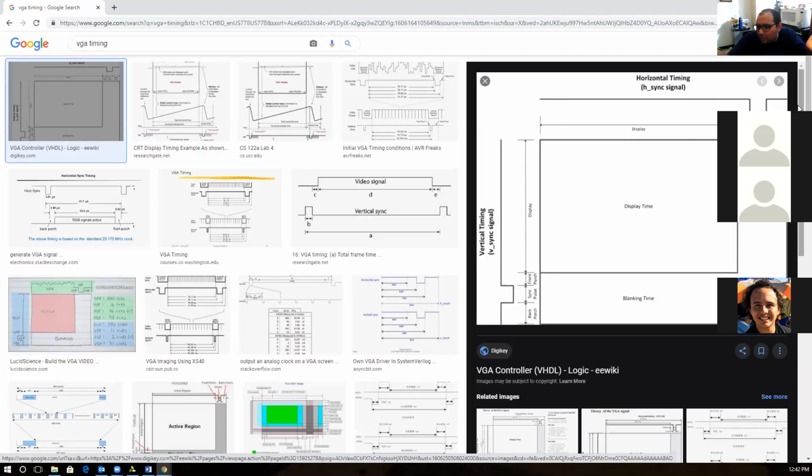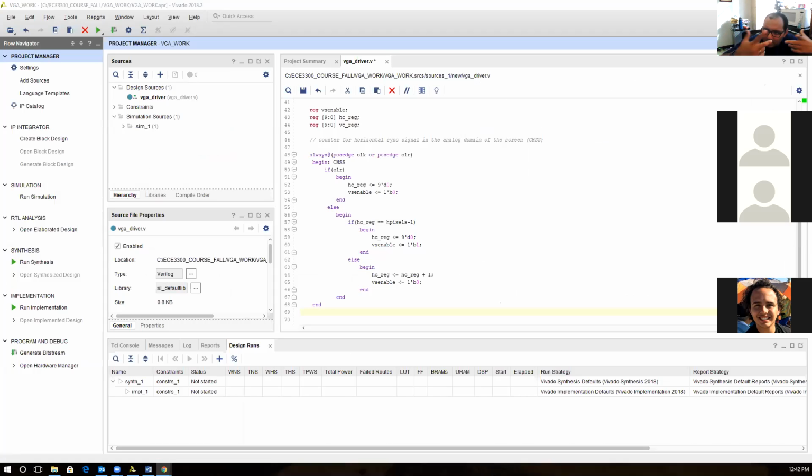So now I need to generate this. I just made a count up to count. I just need to generate the sync of the H signal, which is on high for how many times, including, of course, the display plus the front porch. And then the sync pulse will be going down for an amount of time. Then it will be followed by the back porch. Then they're going to be repeated as much as you can, as the resolution is already made in front of you.